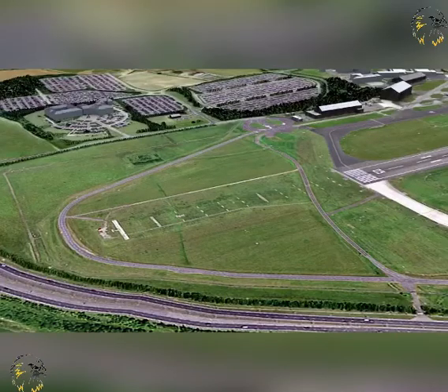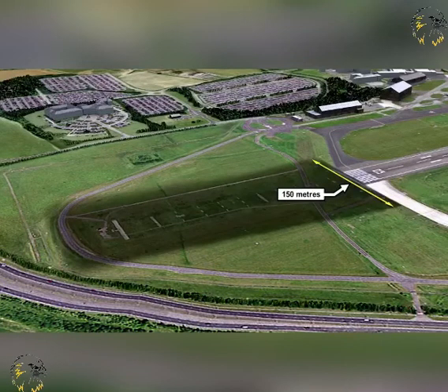Other than a stopway, there is one other additional type of extension that can be made to a runway. This is called a clearway. A clearway is a defined rectangular area beyond the end of the takeoff run available, not less than 150 meters wide, centrally located about the extended centerline of the runway and under the control of the airport authorities.